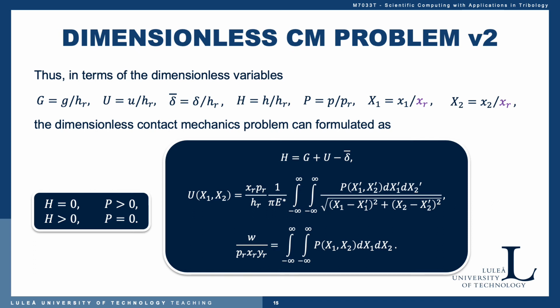By doing this, we have this updated dimensionless contact mechanics problem, and we can see that now we have only two groups left, the 1 and 3, and what remains now is to try to make some educated choices of the reference parameters appearing in these, so that we can obtain as input parameter free a problem as possible.